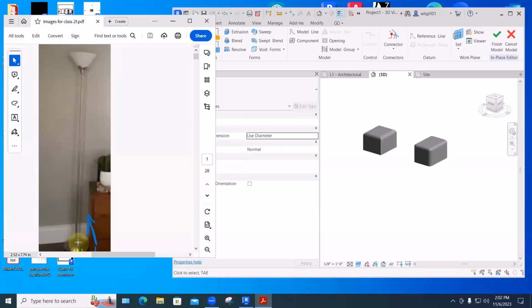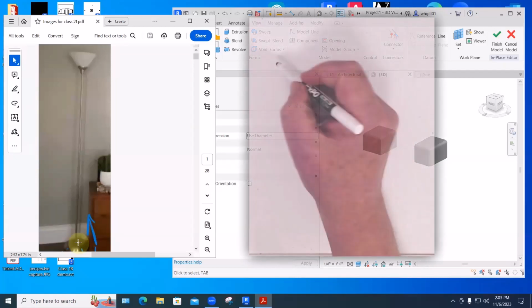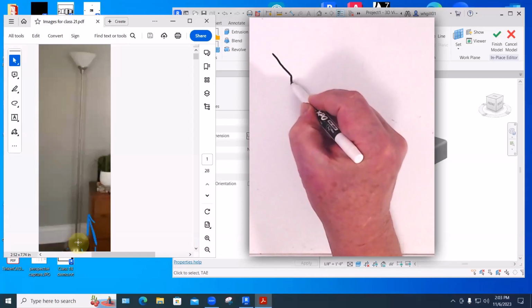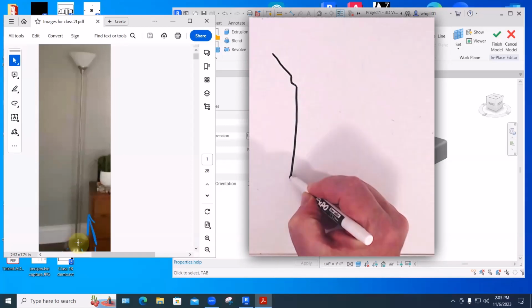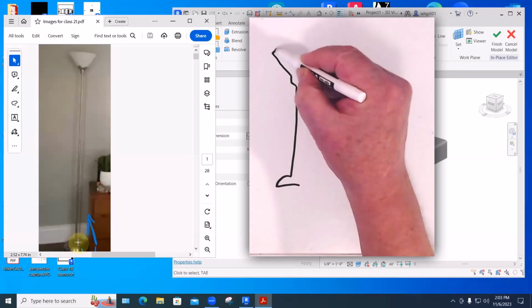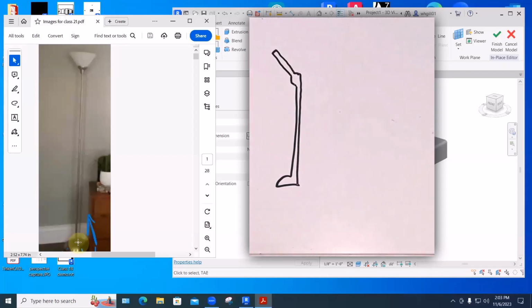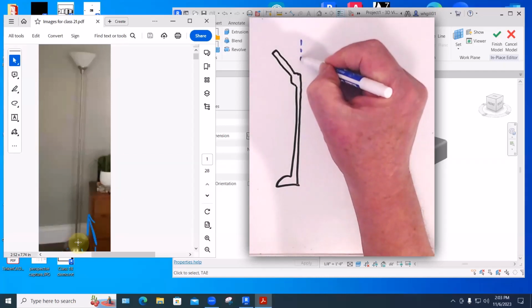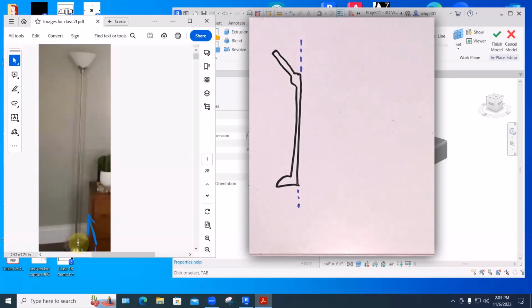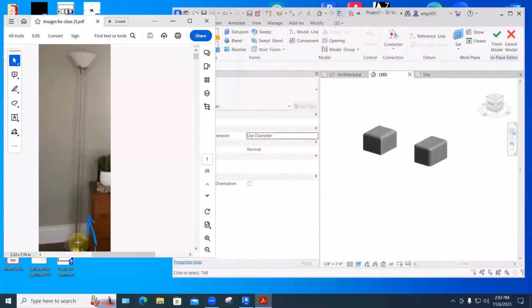And what I realize is, we can also do the stem as a revolve, just like the bottom and top pieces. If we didn't want to deal with this material change at the top, we could do this whole thing as a revolve like this. And here's that center line. And I think keeping track of all the pieces, and especially editing it later on, would be way simpler than a piece and a piece and a piece and a piece. Let's make this as easy on ourselves as we possibly can.